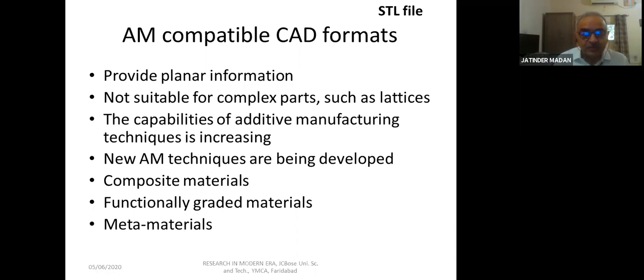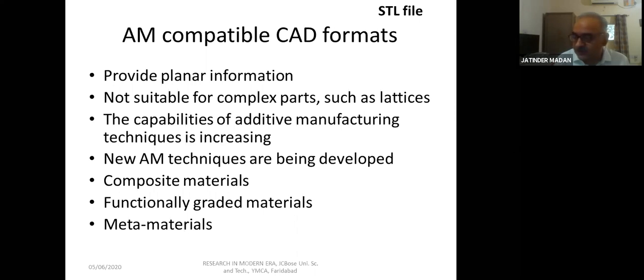Okay, so what you have is a CAD model of the patient's bone, the femur. So you have the CAD model of the area or the bone which you want to replace, and you convert that into an STL file, and print it, maybe in titanium or something, with the help of a 3D printing machine or an AM machine.